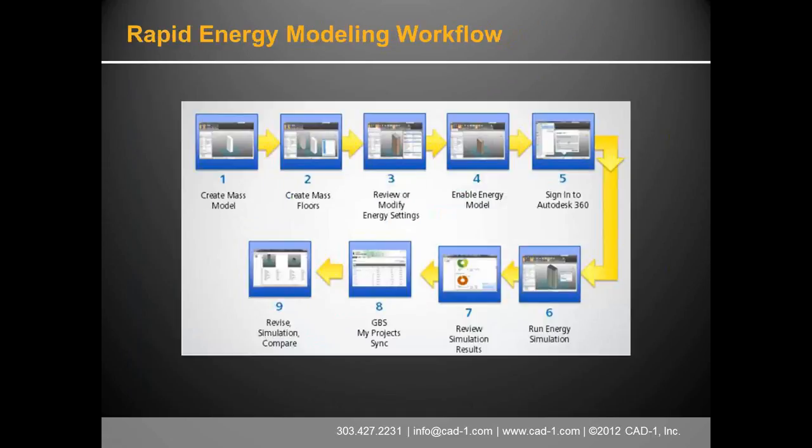And here, Stan, we have the workflow. It's a simple thing on schematic design, so schematic modeling in here. Create your masses, build them up the floor, and then within several minutes of creating those masses, you could start putting them in the energy analysis by going into the 360 account. And then within 10, 15 minutes after that, or faster, it depends on your internet connection and how many processes they're doing, you'll actually get results back, and you can start comparing those with your different iterations, your different alternates that you'd have. And we will go into this. I know those little slides are a little hard to see, so we will go into this in a bit here. Yeah, I'll just open it back up in here.